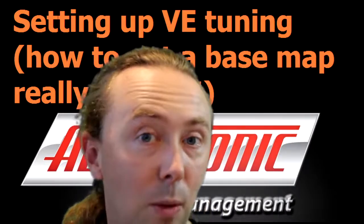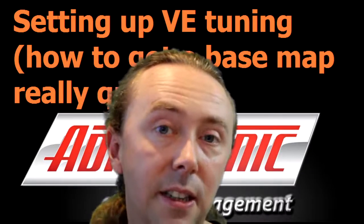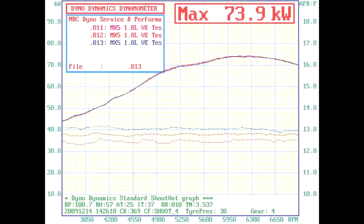So during your tuning, you're trying to adjust the fuel map so that the actual air-fuel ratio matches the target. If the target's not where you want it, then you need to go in and adjust the target air-fuel ratio table. Once this is done, you can adjust your target air-fuel ratios, and the ECU will automatically change the injector milliseconds to compensate.